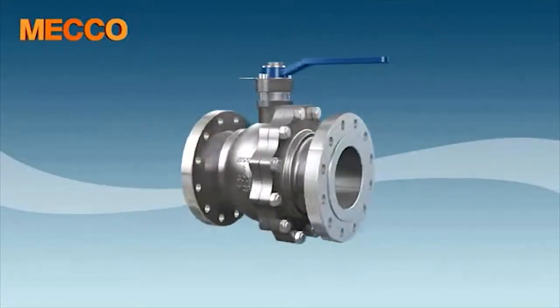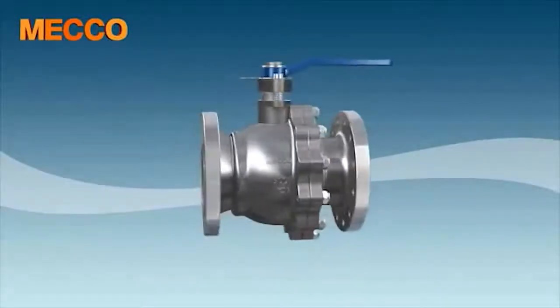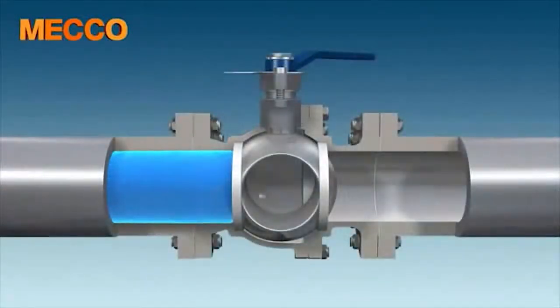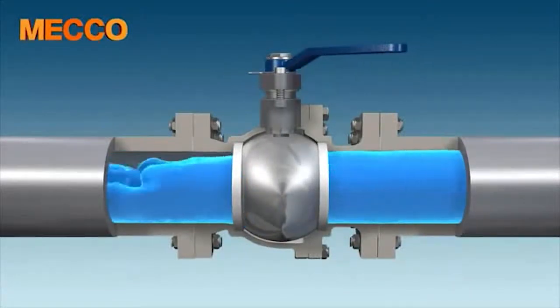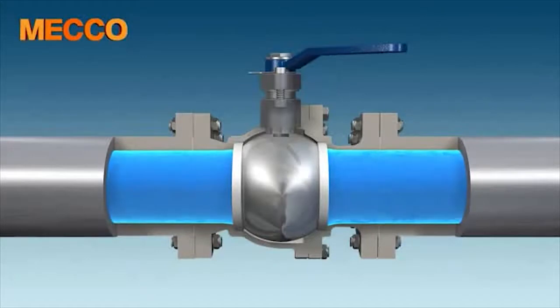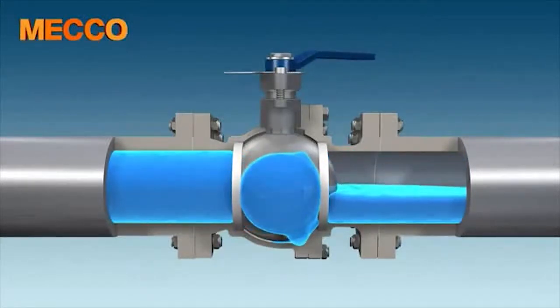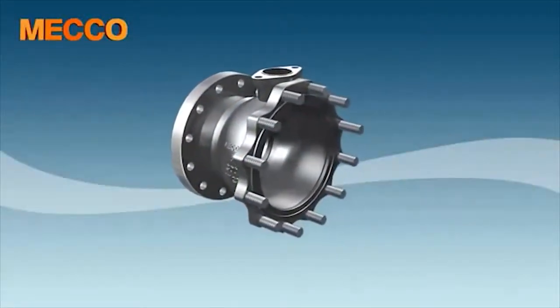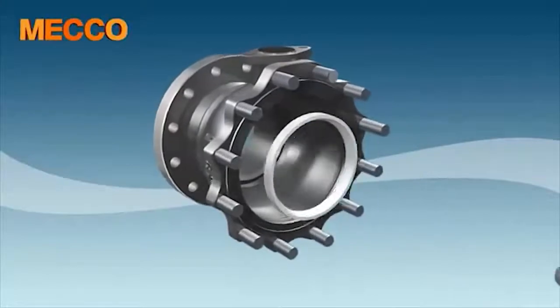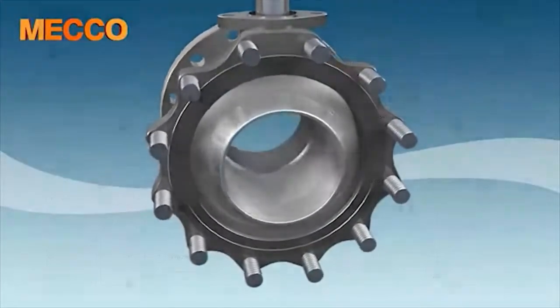The reason why we like to use ball valves is because they have very, very low mechanical complexity compared to other valves that we could use. But one thing that's bad about ball valves is that you can't throttle that well with them. Throttling valves are a lot more expensive hardware, so we're probably never going to bother with them. But this ball valve, as a handle, you turn it 90 degrees, and it opens and closes. It's on-off position is what we use it for.